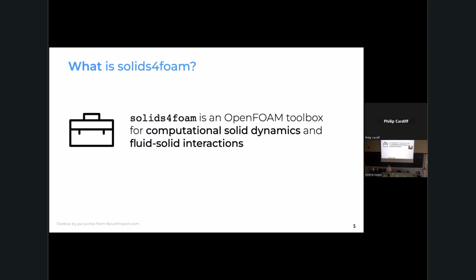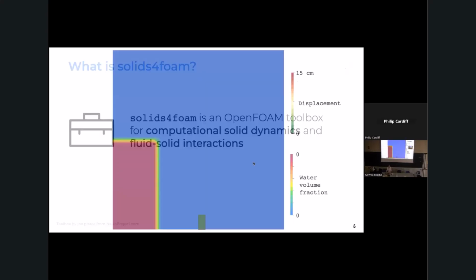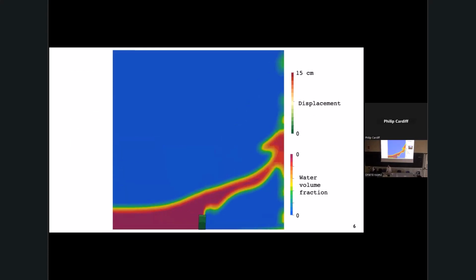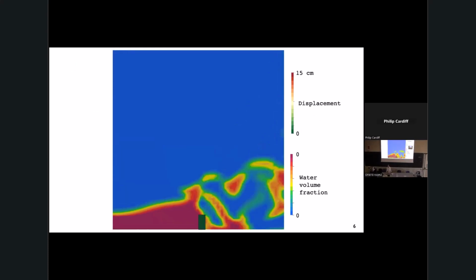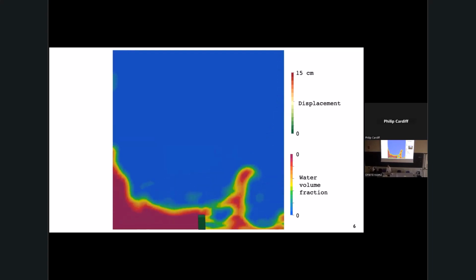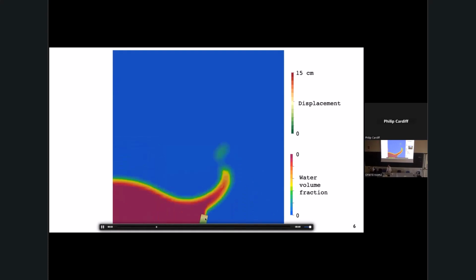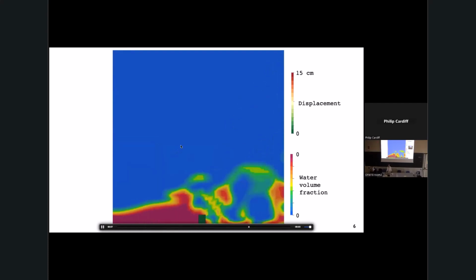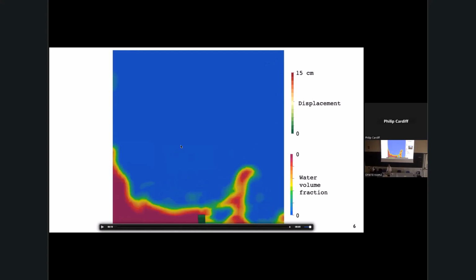This is one of many ways that people can approach FSI in OpenFOAM. For example, everybody's familiar with the dam break example, but you could extend that to a flexible dam break problem, which is also seen in the literature. Here the dam is now a flexible, elastic object, so it doesn't dissipate energy. As the dam breaks, the pressure and viscous forces cause the solid to deform, and the mesh moves as well. So that's different: you need a dynamic meshing procedure for your fluid, and ALE procedures.